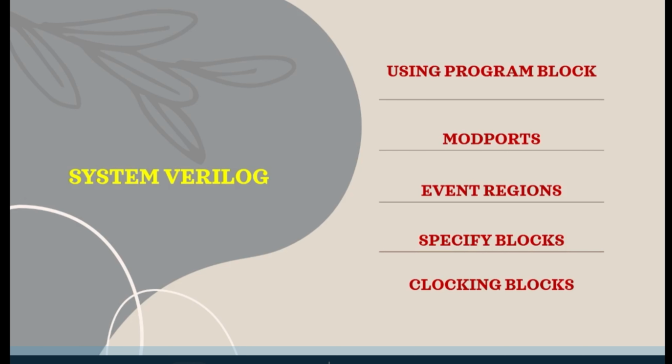So basically, if you're having any timing constraints, by using them in the specify block, it will specify whether all the constraints are executed in the specific timing region or not. So by using specify blocks also you can avoid the race around condition. You will be seeing this keyword called specparam, and it will be included in these specify blocks.